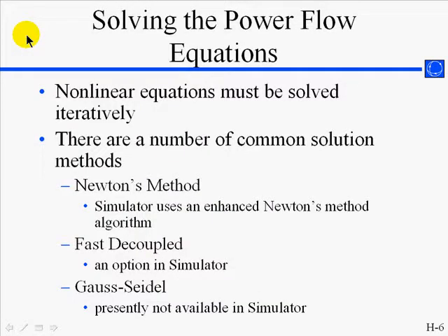Solving this system of nonlinear equations requires an iterative technique. Several solution methods for nonlinear equations are discussed in the academic literature. Newton's method is a very common and popular one that Simulator uses. Simulator can also use a fast decoupled method, and a Gauss-Seidel method is also used in literature, but not in Simulator.